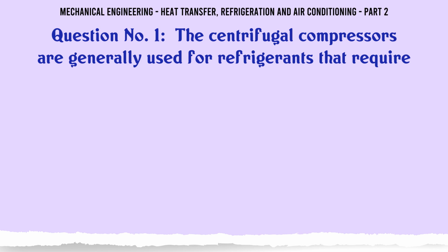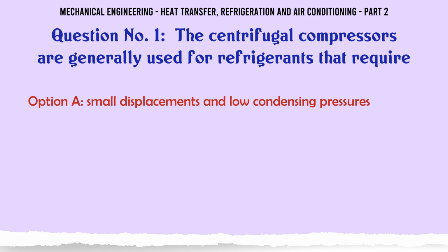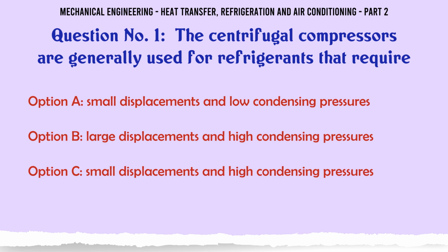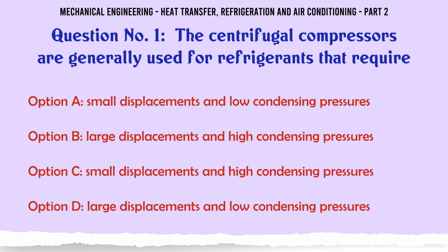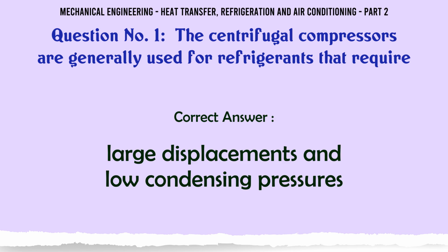The centrifugal compressors are generally used for refrigerants that require: A. Small displacements and low condensing pressures. B. Large displacements and high condensing pressures. C. Small displacements and high condensing pressures. D. Large displacements and low condensing pressures. The correct answer is large displacements and low condensing pressures.